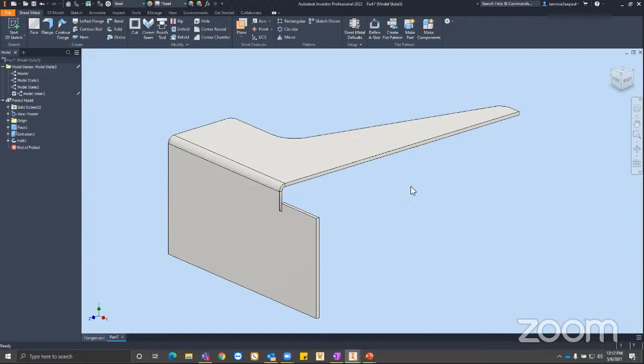Oh, go ahead. Yeah, we actually just had a question come in from the panel from Bennett, and he was wondering why use an extrude versus, say, the sheet metal cut tool. Would there be a preference of one over the other? Honestly, I just prefer the 3D model cut. The sheet metal cuts usually come into play if I know exactly what the machine's going to cut or the path of cutting the sheet metal, because that brings over a little bit of extra information for you.